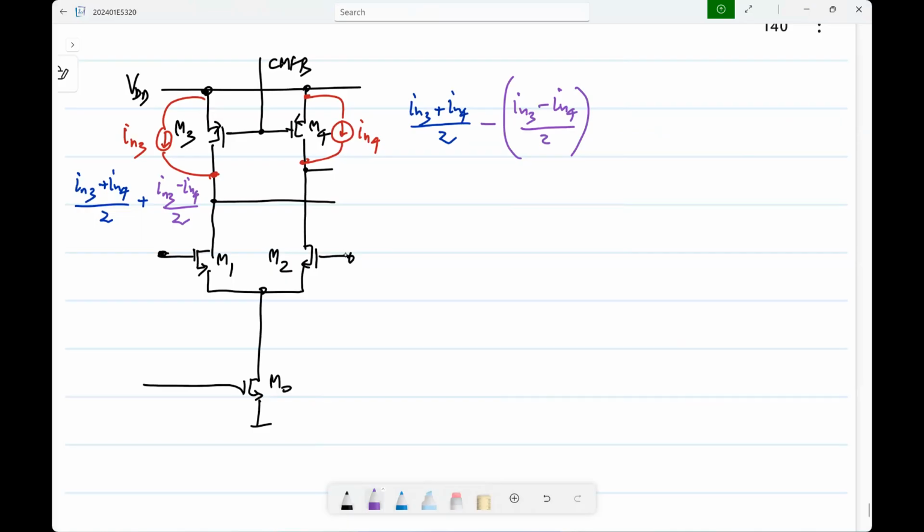So now, of course, you can do the analysis, because anyway, you do noise analysis with the linear small signal equivalent. Okay. So you can have these two sources first and do the analysis, right? And what will be the output noise? Usually it's only the differential output noise that you are concerned with. Okay, there may be special cases where you are concerned with the common mode noise, but the signal is in the differential part, right?